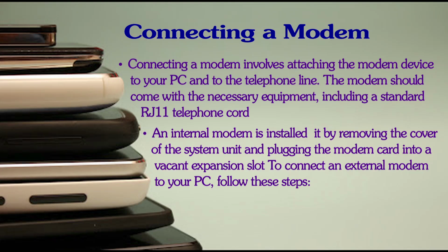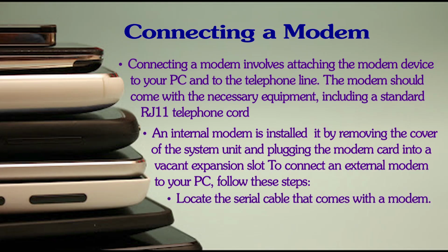Now, for connecting an external modem to your PC, some of the steps are the ones I just explained to you. Locate the serial cable that comes with the modem. It should have a 25 pin male connector at one end and a 25 hole female connector at the other end, and that is something which we have here.